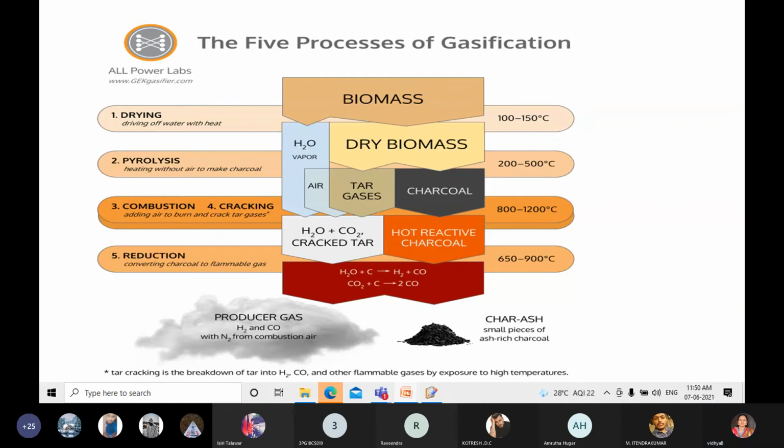Okay, between 200 and 500, only then do we get large quantities of tar and gases containing carbon dioxide. Okay, and between 500 to 700 the gas production is small and contains hydrogen. And in the next, the combustion process, we get carbon.